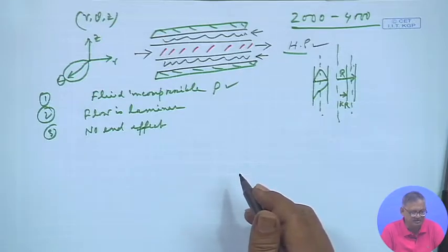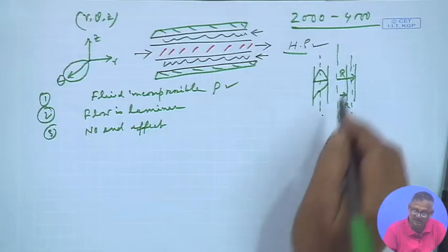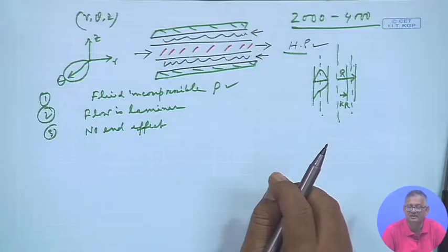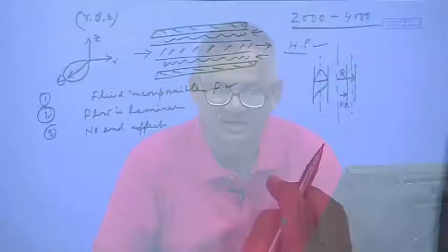If we take a momentum balance in this, we can start with, as we said earlier, that in many cases instead of doing all the force balances from the beginning every time, using the governing equation: rate of momentum in minus rate of momentum out plus sum of the forces acting on it equals rate of momentum accumulation.